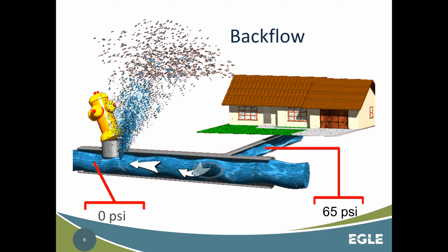So that backflow event that we're seeing here, the water's going to run out of the house, and then it's going to come out here. We know that this is not supposed to happen. You don't hit a hydrant, it's supposed to blow out water. This is a Hollywood picture, just so we're all aware, because this would break away the shackle and it would close the bottom valve so that it wouldn't gush water. But anyway, this is a backflow event as back siphonage.